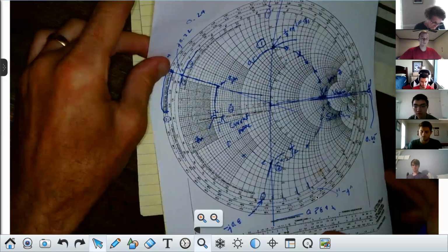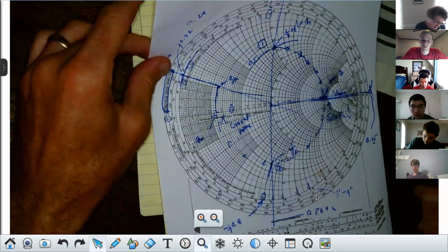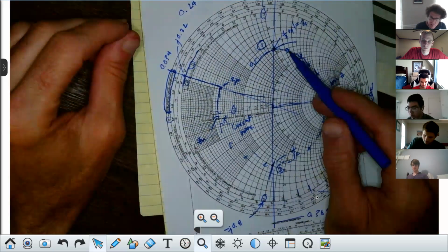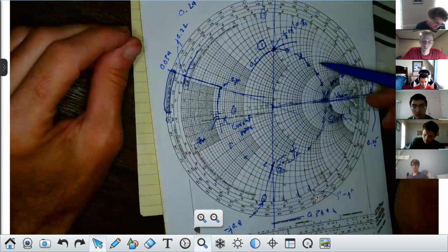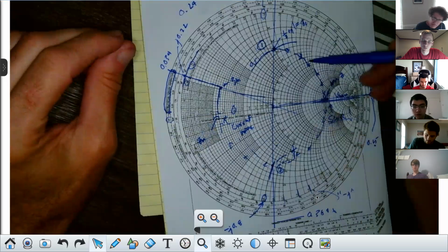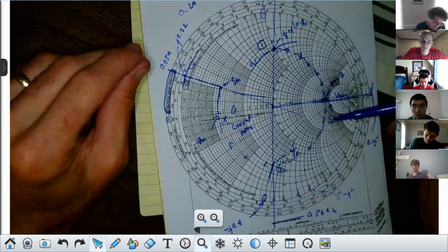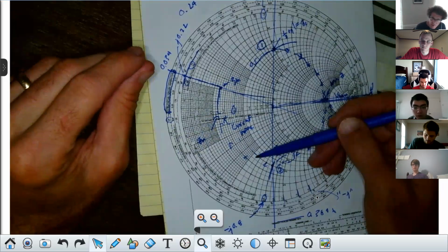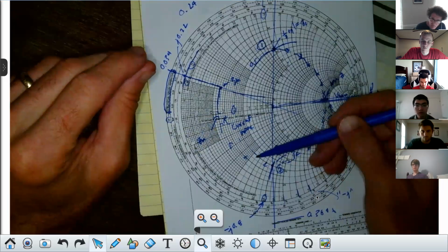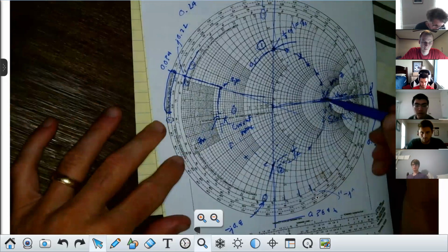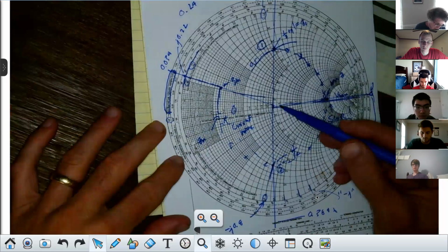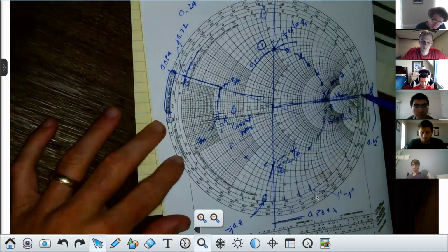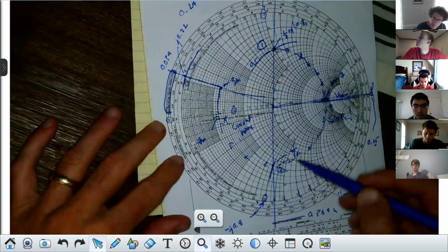Now, we went through how you get into the Smith chart and normalize. We went through how you find the impedance going along that circle of constant radius, or really it's the magnitude of reflection coefficient. How you can get the impedance anywhere, correct? Now what we're going to do is find out how you would go about using a Smith chart. Something else, we found the maximum value of the voltage, and the standing wave ratio is right here where it crosses the axis between the center and the rightmost part of the Smith chart, or the equator on the right. And we found the minimum value impedance over here, right?